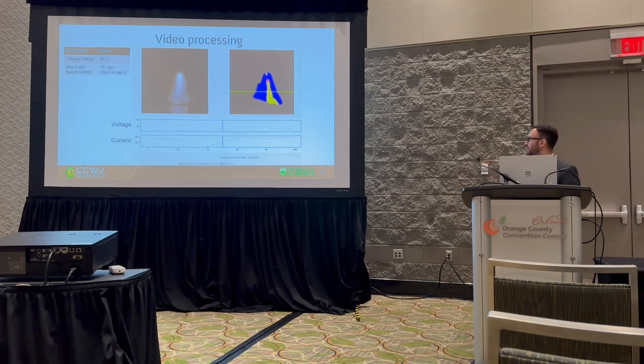And it's quite valuable because now you can get a real appreciation and quantifiable data per frame. So here you start to see that this droplet is going to come into contact with that line, and you're going to see this droplet count increase by 1. So now we can start counting the droplets. We can start getting more data in terms of frequency and cross-section of the area of the droplets.